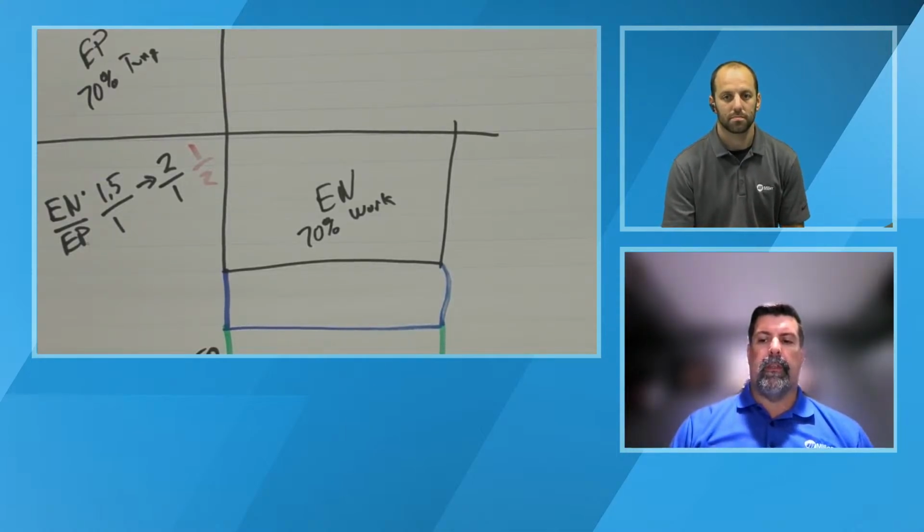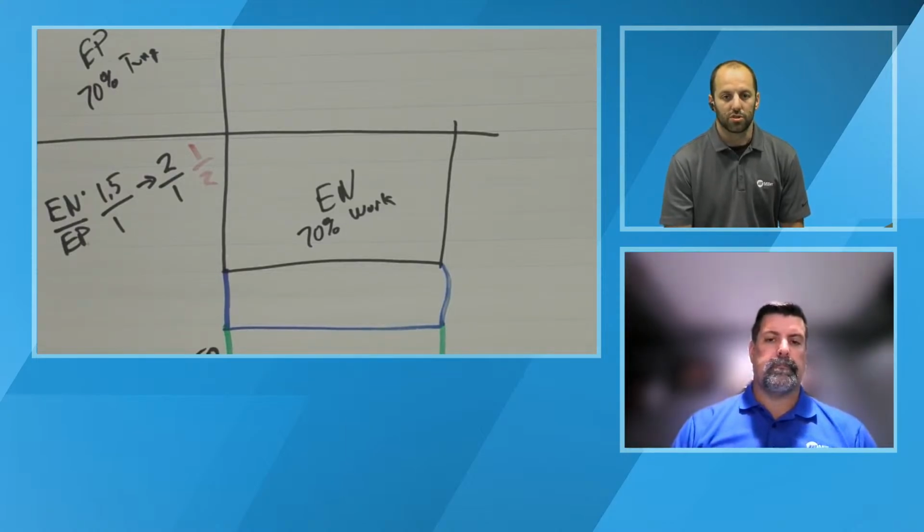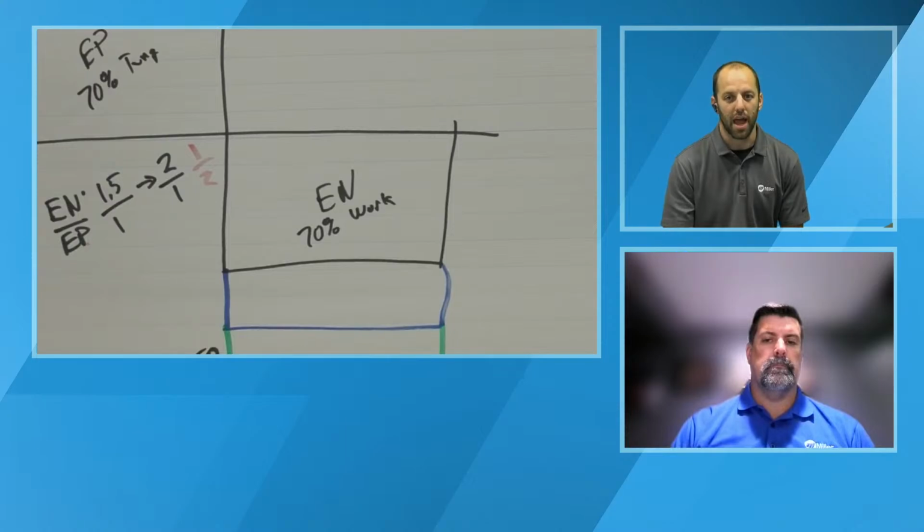Okay. One last question before we move on to the next topic. What was the material thickness that we're speaking about here for balling? Generally, if you're looking at balling the tungsten, you're probably going to be 3/8 or 1/2 inch and above. Typically, if you're under 3/8 of an inch, you're going to be running more of a truncated shape versus a 1 diameter ball or maybe even a little bit larger diameter than your tungsten.